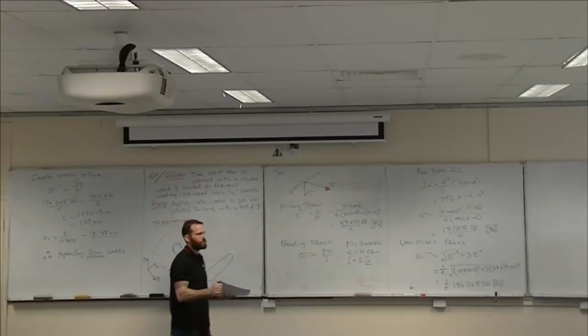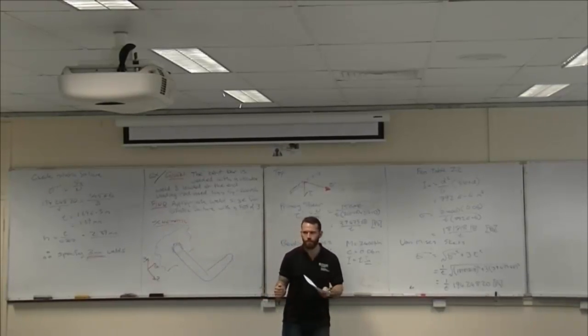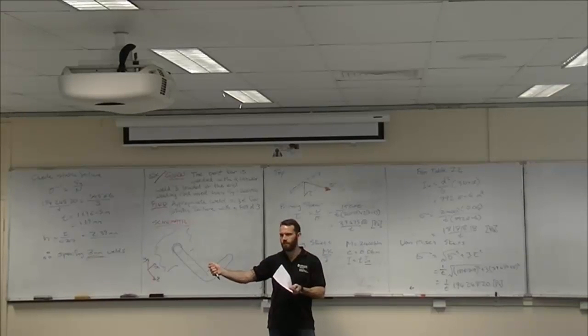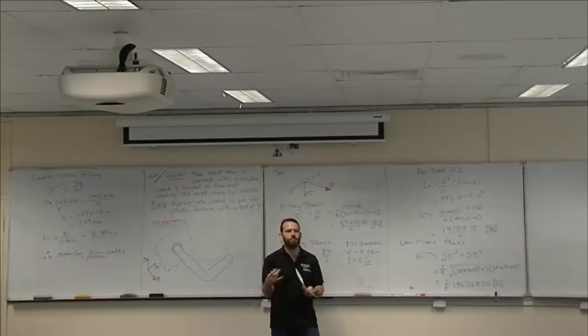As you'll see, by the time we go through bolts and gears, you'll see that we're doing literally the same workflow every single time. So what are the forces, how do you characterise force? What are the stresses, where's the critical stress, what affects that? How do you compare to the failure criterion? What are sigma A and sigma M in the critical zone? Is it failing? That workflow repeats for literally every machine component.